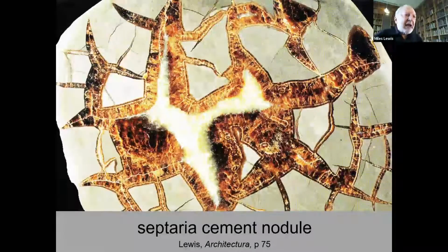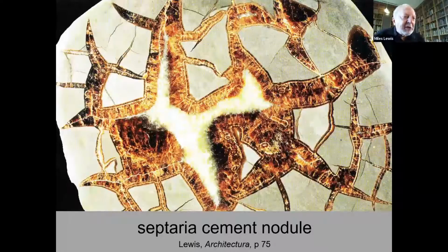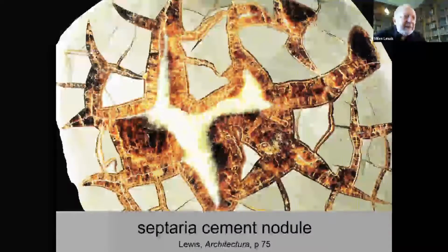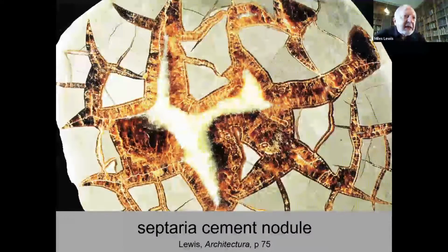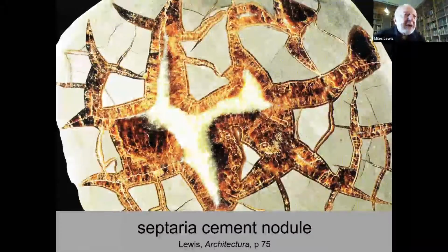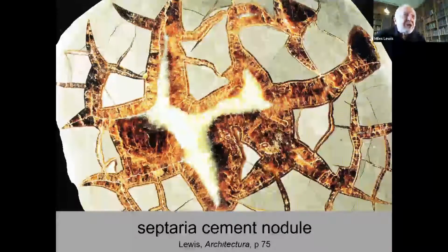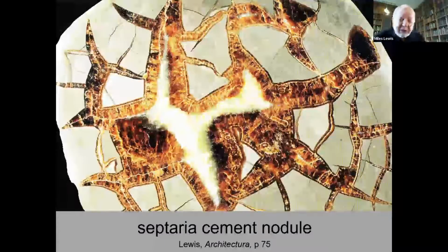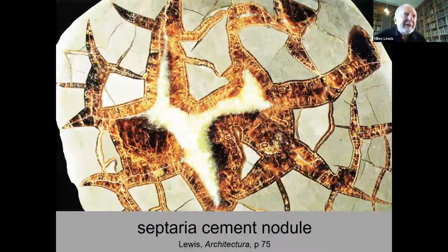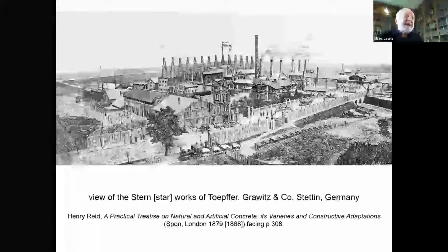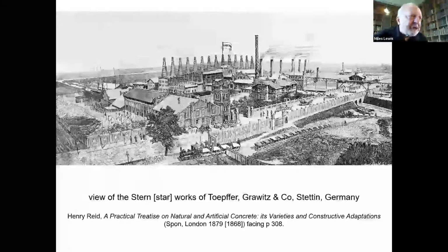And there's every gradation now from common limes through this hydraulic lime, so-called Roman cement, natural cement, which occurs because the stone naturally has these materials in it, to artificial cement, where you actually choose the components and you mix the cement you want before you burn it. And that's what's done in the late 19th century in artificial cement works.